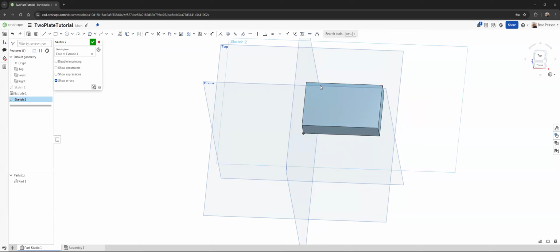So select this top face. All right, I'm in it. So I am sketching. I'm not going to reorient it. Sometimes in SolidWorks for simple things I wouldn't. So let's grab the point here and drop some points in. Point, point, point, point. Now I want to try to constrain these things the way I would in SolidWorks. In SolidWorks, I would constrain these vertically, these 2 pairs, and then horizontally these 2 pairs, and then start to dimension. So let's select and see what it'll let me do.